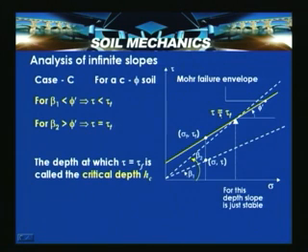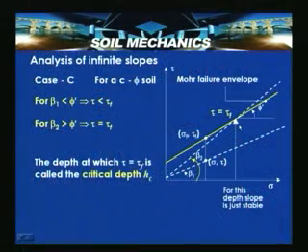So, in the tau-sigma plot, similar to the previous slides, we represent the Mohr failure envelope and consider soil surfaces with different slope inclinations. As long as beta 2 is equal to phi', the slope has just attained failure. Once beta 2 is greater than phi', it attains tau equal to tau f somewhere here, beyond which the slope would have already failed at all depths.